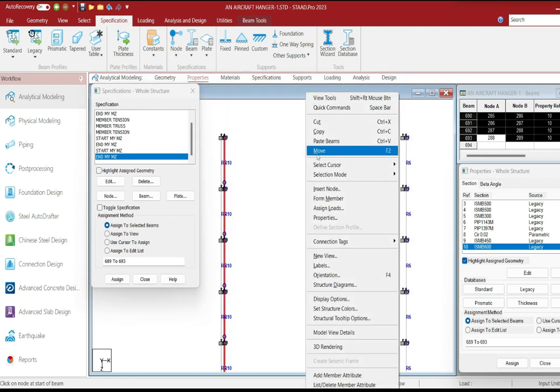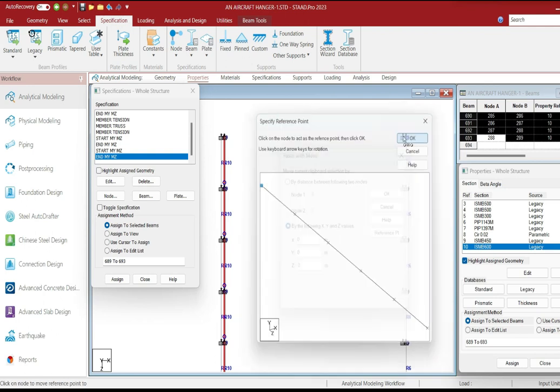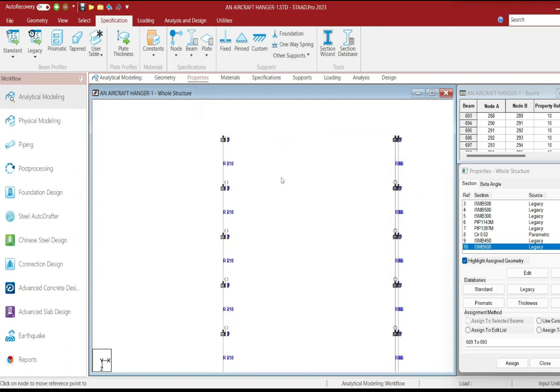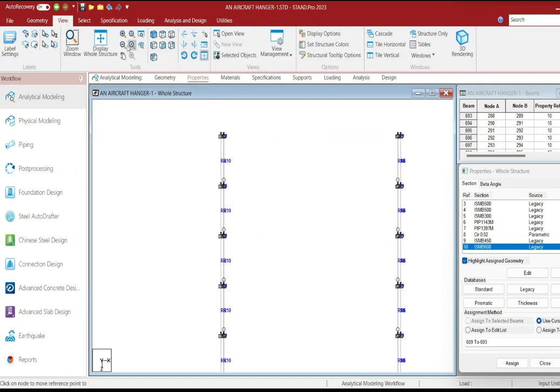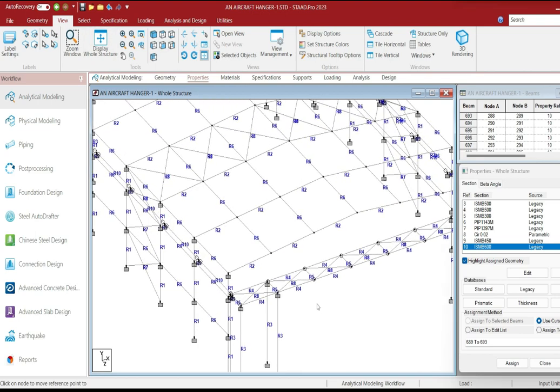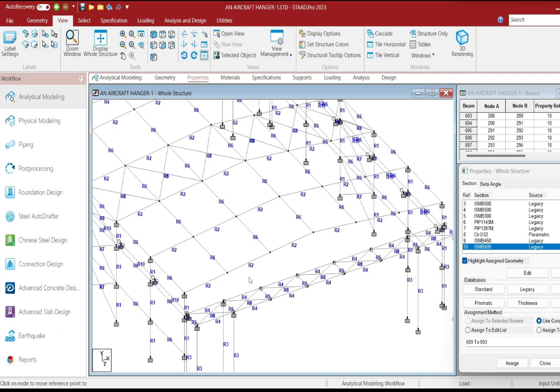So now copy this gantry girder to the other side also. So the gantry girder at the bracket top level has been created. As of now, these are standard sections; we will change them to the design sections at a later stage when we perform the design. Now, the last part is we have to make vertical members at the gable end to provide closure for this part, so that a guard can run along this.